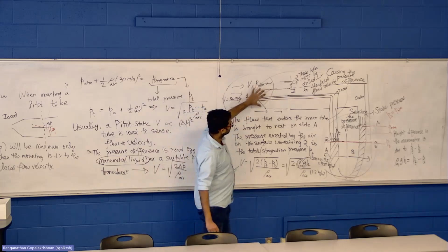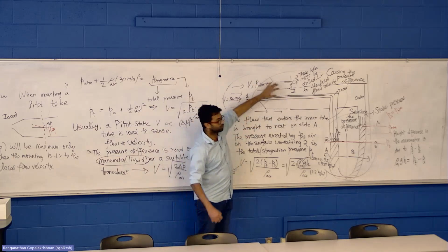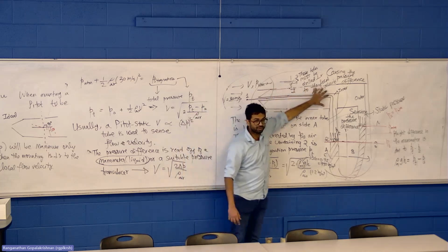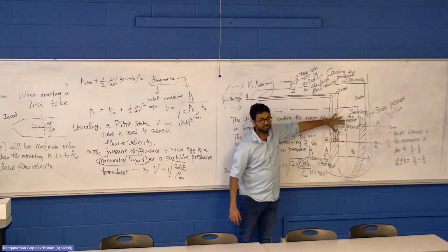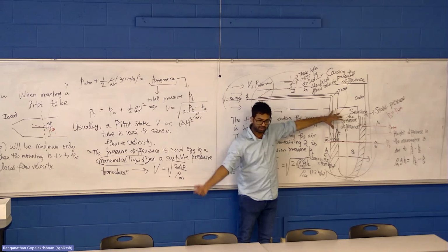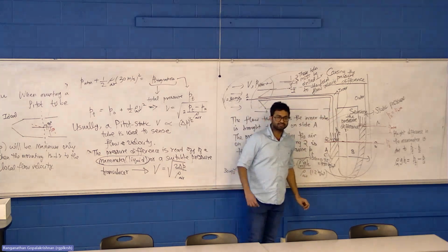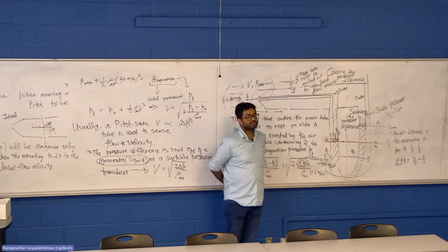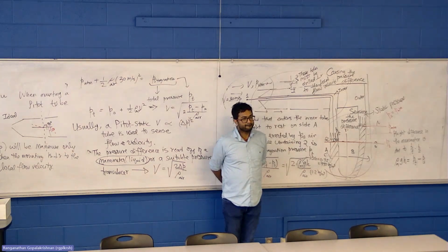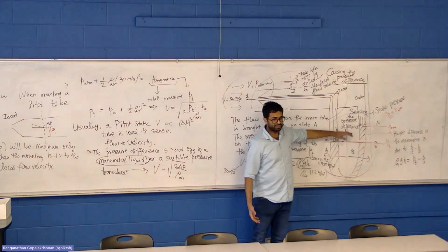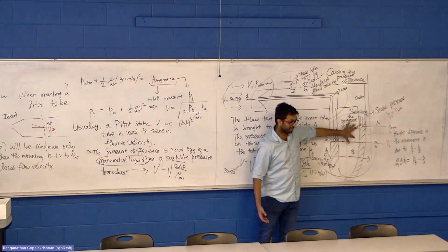We talked about how the Pitot tube has two components, if you recognize. The sensing element, sorry, the structure that is sensing the pressure difference, and the transducer which is used for sensing, the manometer being the most common transducer for pressure. Now, is the manometer an analog or a digital device? Why do you say it is analog? It is not based on electronics, first of all. It's a physical instrument where a liquid responds to the pressure change.